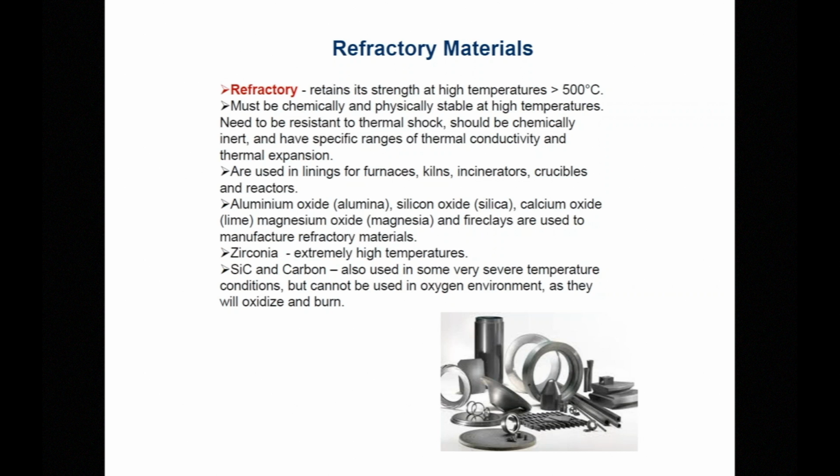Zirconia is sometimes used for extremely high temperatures. Silicon carbide and carbon are also used for very severe temperature conditions, but the problem is it cannot resist any oxygen in their environment. Otherwise, they easily oxidize and, of course, combust or burn.